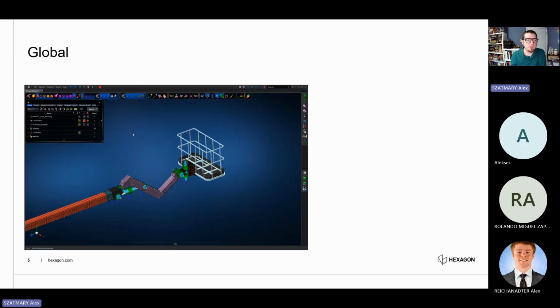One of the keys for this model that we can see in the video is that there are a lot of not just solid elements, but mostly shell and beam elements, which are very economical. You also might notice connectors being assigned, multiple coordinate systems being used, and Apex is really great for setting up that kind of a model.